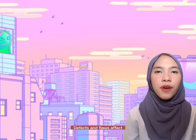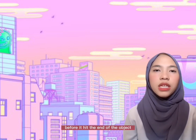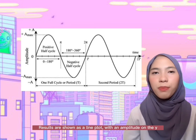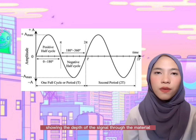Defects and flaws affect its way, and a small portion of the pulse will be sent back to the transducer before it hits the end of the object. Results are shown as a line plot with amplitude on the y-axis representing the reflection intensity and time on the x-axis, showing the depth of the signal in the material.